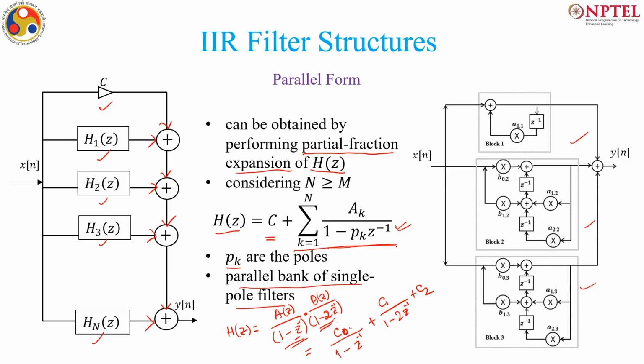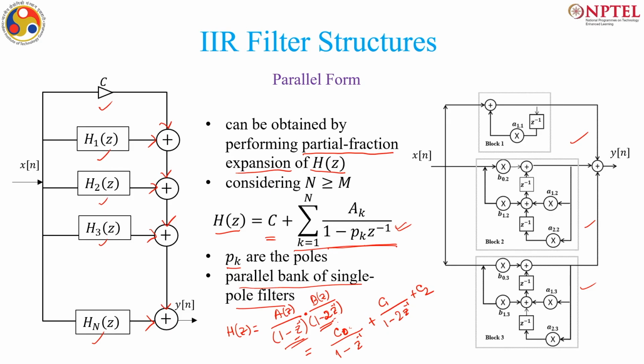Now, so far the direct form was there in the FIR case, and we got 2 direct forms in the IIR case, because there are cascades of an FIR and an all pole, and by the interchange of these filters we get 2 direct forms. Again similarly, by changing these branchings we got the transposed form. Cascade form also was there in the FIR system, and in the IIR also we got the cascade form. We are studying something new as the parallel form in the IIR case, but is there a parallel form possible